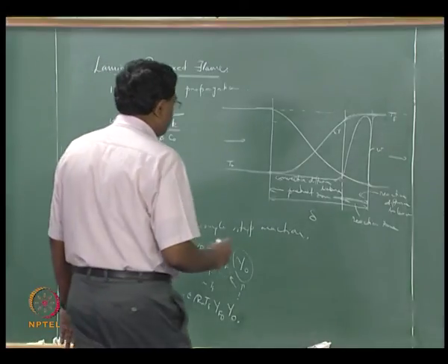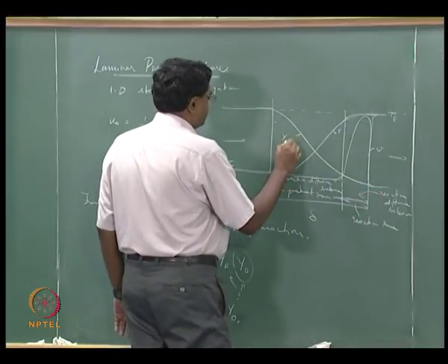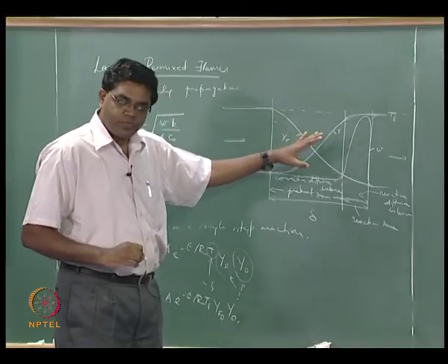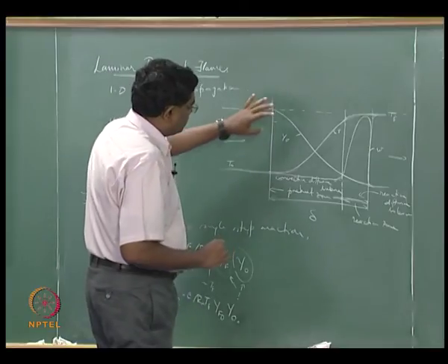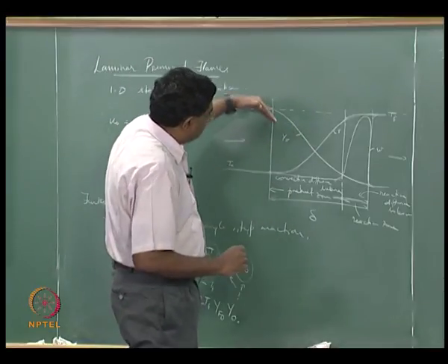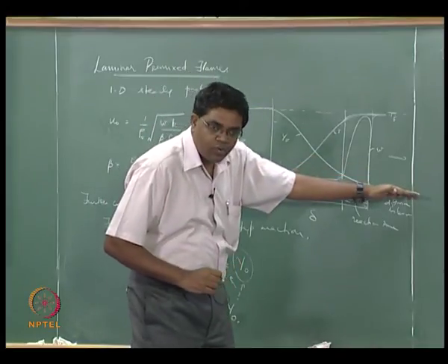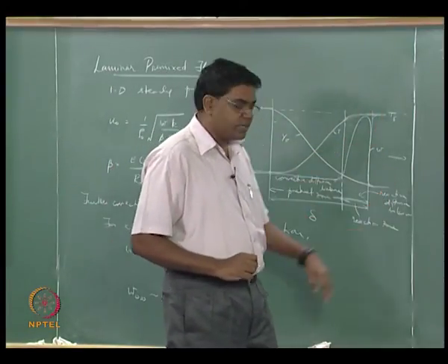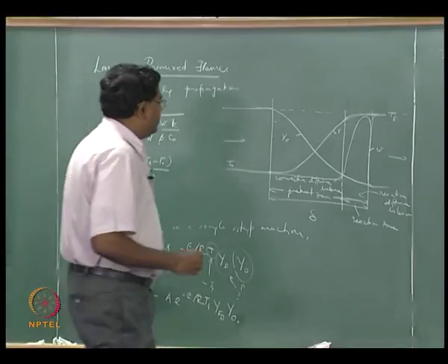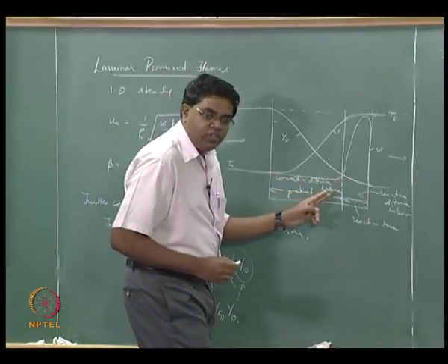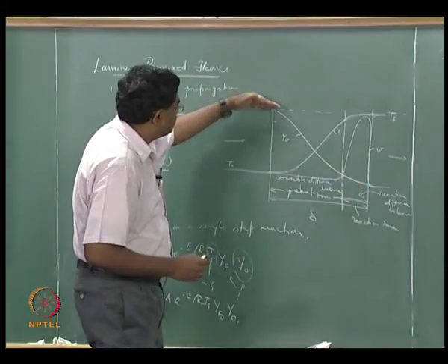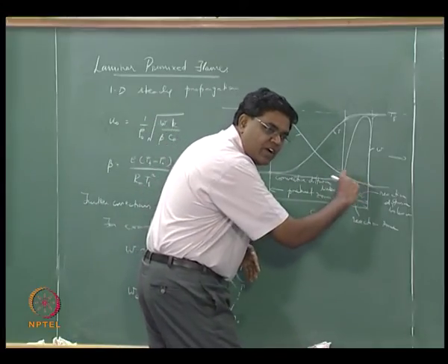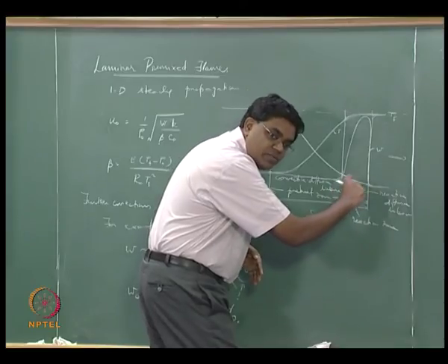Now this is obviously for the deficient reaction. Let us suppose that we are considering a fuel lean situation, okay. If you now consider a fuel lean situation, then that species concentration mass fraction is going to go all the way to 0, and that is the reason why your W is also going to 0 at the end of the reaction zone, right. So now look at what happens to the species mass fraction variation within the reaction zone. Instead of actually having a value that is about that high, you are now looking at a value that is about so small, okay. There is hardly any variation of this away from 0, so we are now talking about fairly small values.